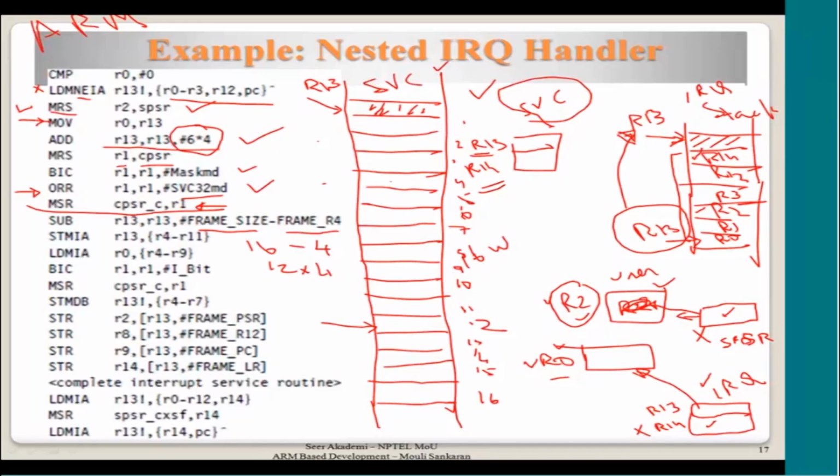During the second level of interrupt handling we want to enable the interrupt, but we still have not enabled it. So before enabling the interrupt, we modified R13 to go back to the original place. The contents are already in the stack and not disturbed, and since IRQ is not enabled, this content will not be disturbed by anybody modifying the value of R13 and pushing something into it.